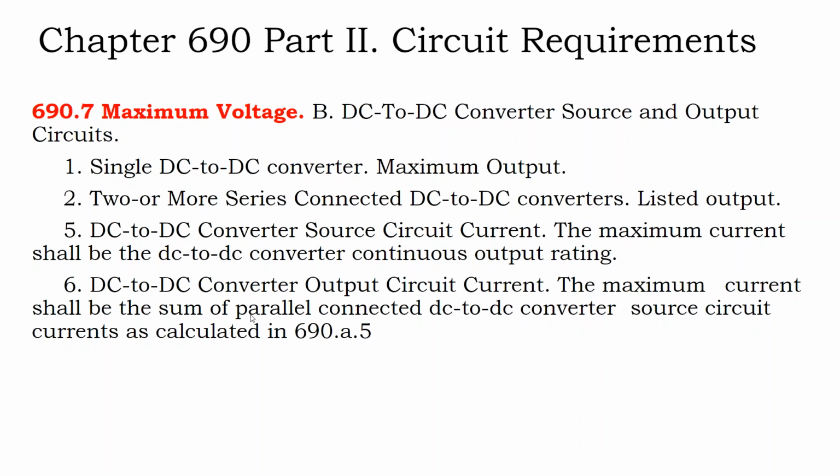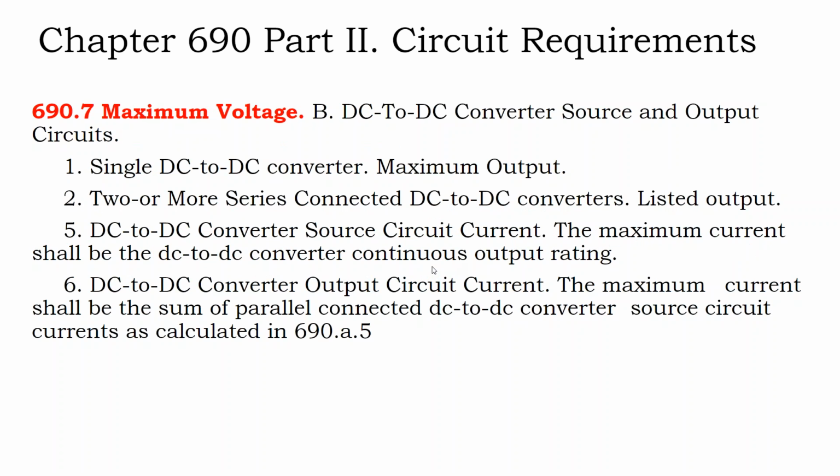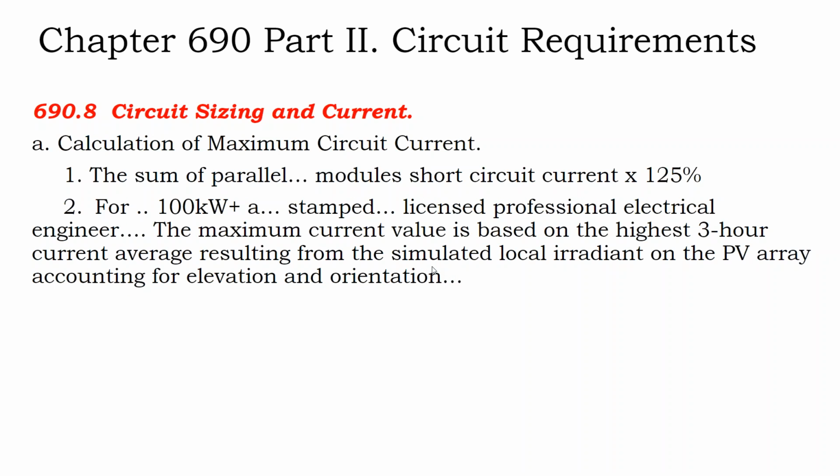And if it fails, it fails to 1 volt rather than full voltage. So it's just fine if it fails correctly. And so code allows your optimizers to have longer circuits because they are providing additional inline controls to regulate voltage and amperage to stay within that 600 volt threshold.